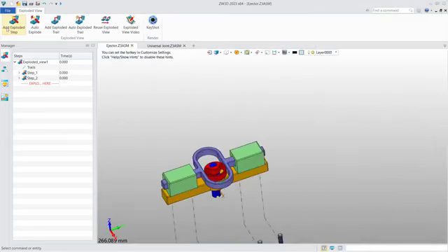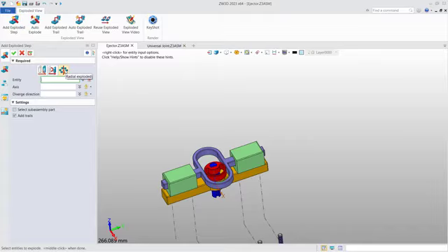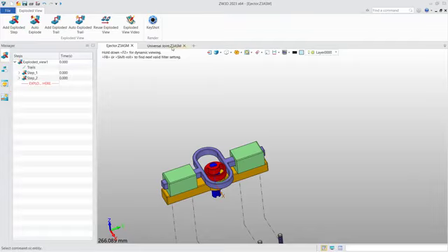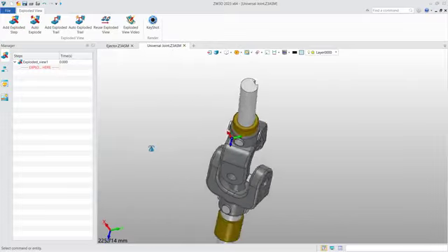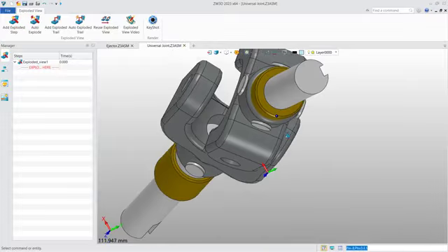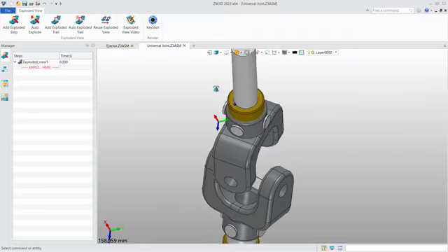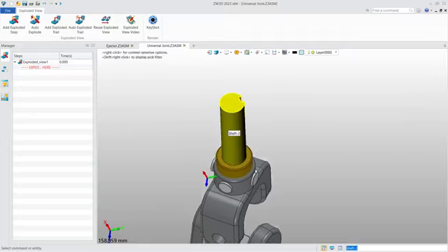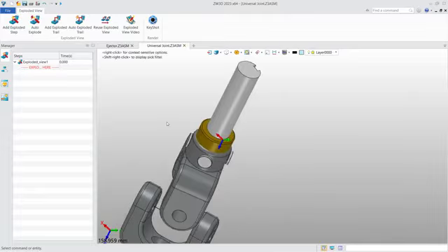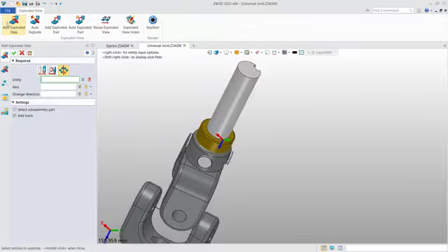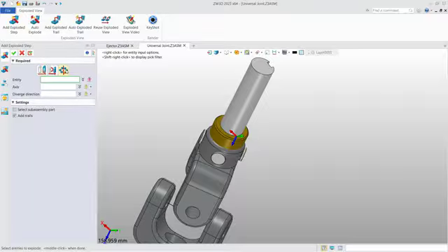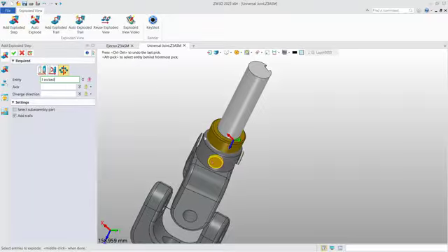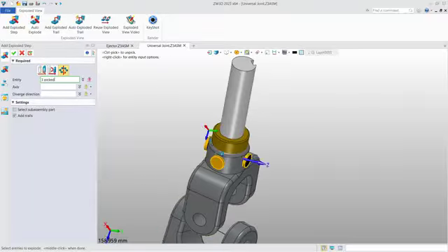And for the last one, which is radial explosion, I think I can use another case to show you. Okay, we use this case. You can see for these 4 bolts, we want to move around this axis, but in different direction. Now let's see how to use it. Add exploded step and entities. We select the 4 bolts.